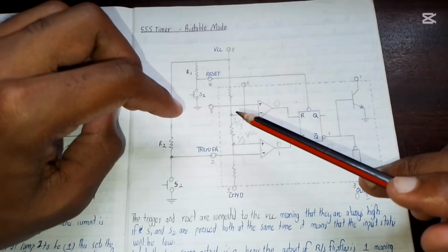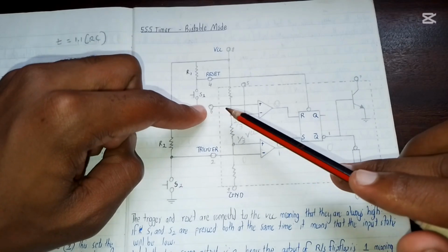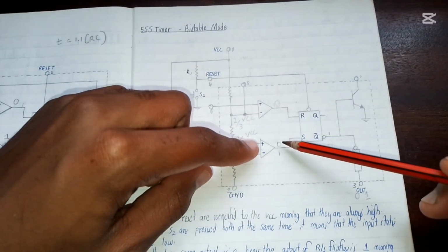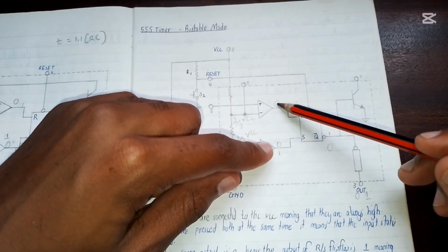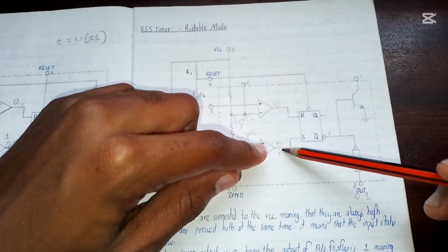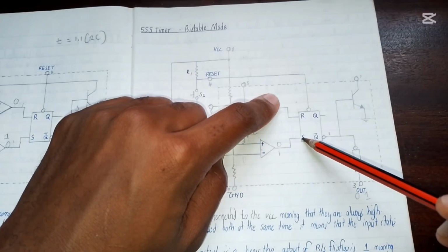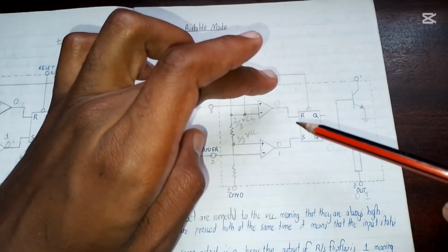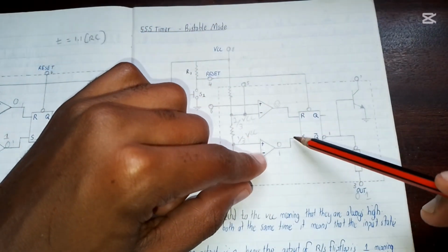Why? Remember we said that the threshold pin is 0 at all times because we have not connected it. And since this comparator is giving a 0, the output is not going to change. It's not going to change because this has to be 1 in order for it to change in what you give at the input right here. So if you give 1 right here, then that is the only time when the output will be changing the input which you have here.